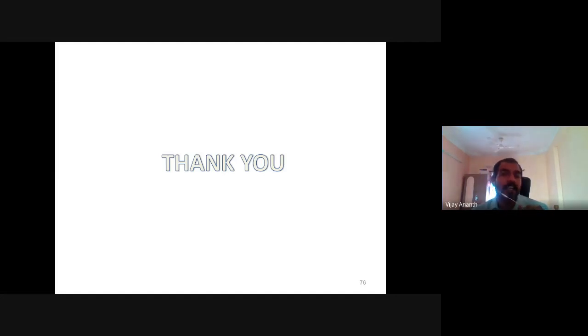Suppose we are working with new materials, like I have done with aluminum silicon carbide composites and aluminum 6063 alloy. I have done this with the trial and error method. At 520 degrees centigrade, I obtained a very minimum amount of elongation. I obtained up to 600 degrees, but the components failed. But at 580 degrees centigrade, we get a very good superplastic forming. So this is by the trial and error method. But for many alloys, the data is available in the literature, sir.